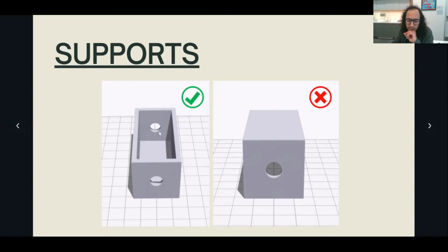You would probably have to experiment depending on your filament, play with the temperature, the speed, and the cooling. And then, like I said, usually lowering the temperature and the speed will give it more time to solidify so it has a solid foundation to work on.